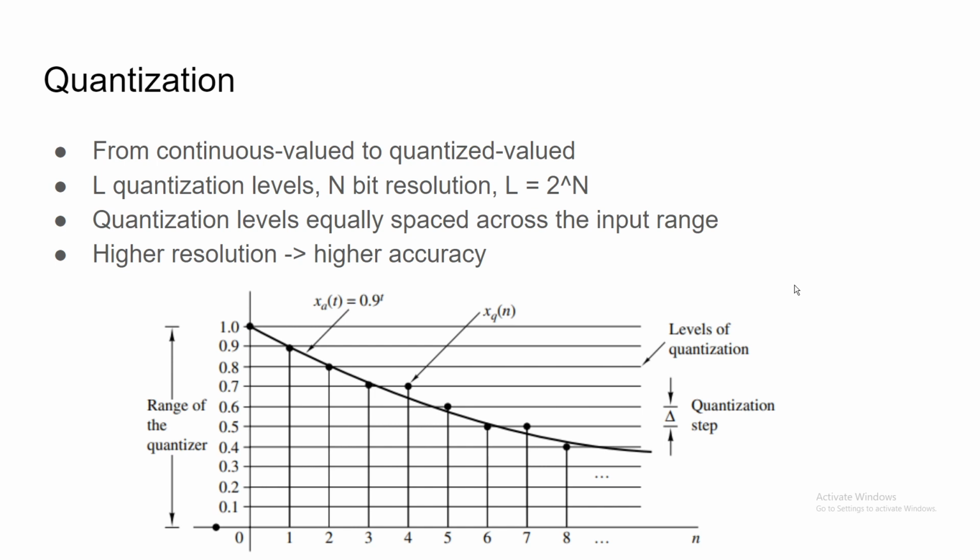First, we make the assumption that our input signal is uniformly distributed. With this assumption, in order to ensure that we minimize the distance between the input value and the output value, we must also choose a set of outputs that is uniformly distributed across the input range, like in this figure. Each of these steps is a quantization level, and the difference between neighboring quantization levels is called the quantization step.